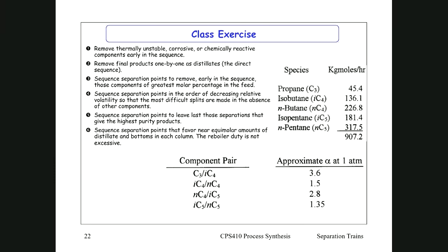So the thing about the largest molar percentage of the feed, can you expand that to splitting streams into the smallest possible side streams so that you don't have one massive stream going along, because that implies bigger columns? If you can halve the total amount into two separate streams, you have a series of smaller columns. Is that the reasoning behind splitting the large amounts early?